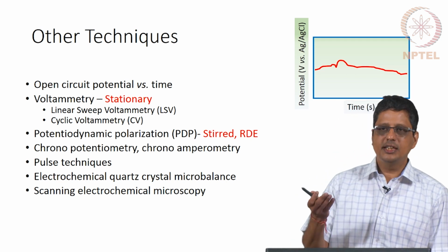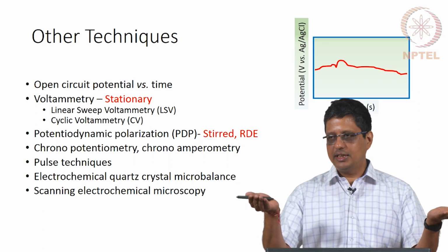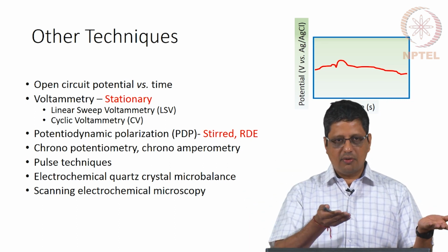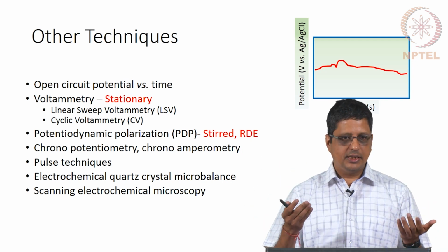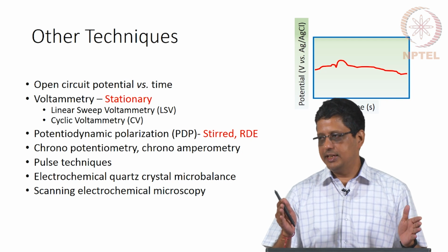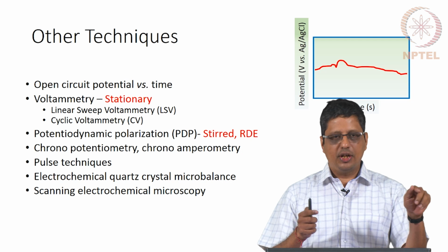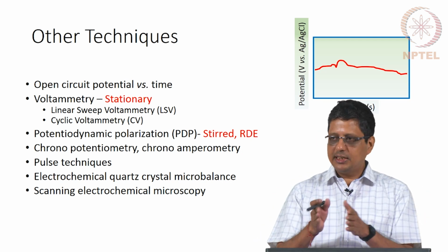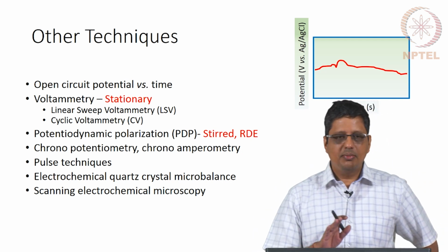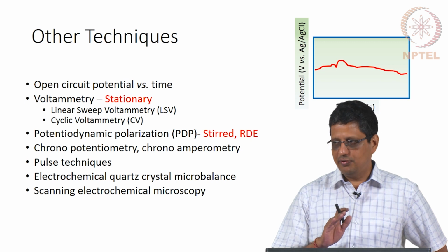So, it is essentially saying, I know how the system behaves from zero frequency to infinite frequency. So, if you tell me I am going to apply a triangular wave, or a rectangular pulse, then I can reconstruct it using a method called Fourier series. In Fourier series you can add multiple sine waves to reconstruct a particular periodic shape. Then you can basically say, by adding the responses I can get the result. But then electrochemical systems are usually not linear and this will not always work.